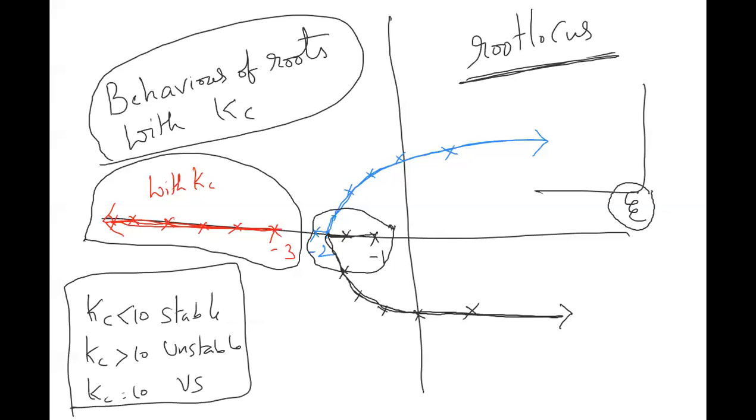Suppose you are talking about small plants, if you are working in R&D, you do not have that many inputs and outputs. You may have, let's say, we are doing a simple experiment, 10 inputs and 10 outputs. Then you don't need a DCS, you need a PLC panel. PLC means when the number of inputs and outputs are very small.